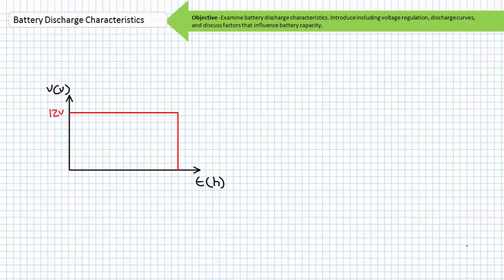The discharge process exhausts the chemically active materials, in such time the reaction slows down and eventually ceases. In a perfect world, a 12-volt battery would provide a constant current at a constant 12 volts for a predetermined length of time, and then simply drop off and cease to function. This is essentially the logic behind the amp-hour capacity rating of a battery. It basically ignores voltage variation of the battery, and a user is left to assume a nominal value.